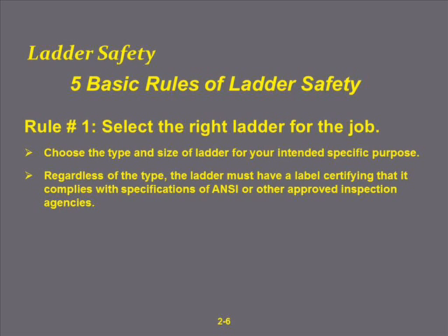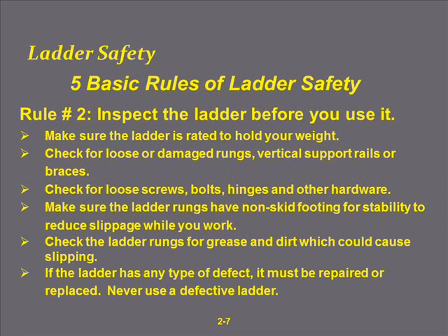Next, we have our 5 basic rules of ladder safety. Rule number 1, select the right ladder for the job. Choose the type and size of ladder for your intended specific purpose. Rule number 2, inspect the ladder before you use it.